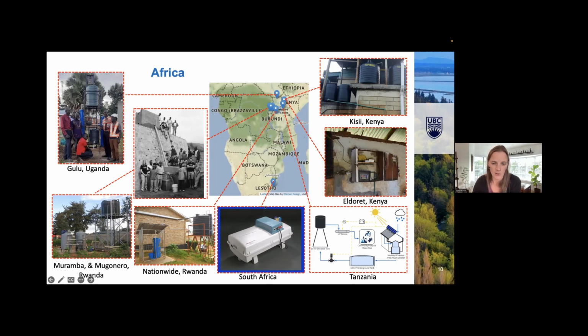In South Africa, I also talk about this one in more detail. This was one of the UV waterworks. You'll hear me mention that a couple times because it was used first in India, and then the second iteration was done for an orphanage in South Africa. And so here, one of the things that's unique about this is that they had the UV lamp above the water, and that was to help reduce or prevent the impact of scaling or fouling of the UV lamp sleeve. This is a low pressure UV lamp. So that's one thing that was unique to that case study. But I'll talk about that one in more detail. This was in KwaZulu-Natal, and it was with Lawrence Berkeley National Labs.